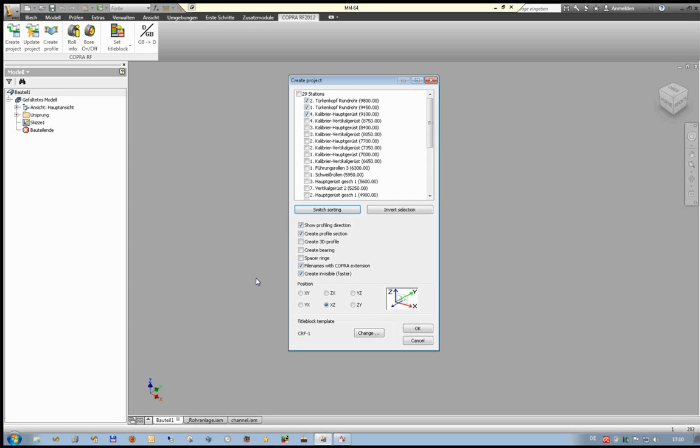If you don't set the invisible flag, then each role that gets created is also showing up in Inventor. It's opened, it's changed, it's closed, then the next one. So in this case, you will see what's going on, but on the other side, Inventor has to create all this graphical information, and it's a little bit slower.